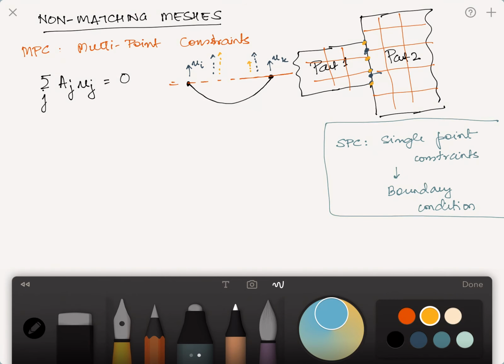So the equation in that case would actually look like this, for both cases. In the first case, the blue case, case 1, let me write it with a blue pen, then it's probably easier. So in case blue, where UI and UK have to move together and by the same amount, then I have A of UI minus A of UK is equal to 0, because they have to move exactly the same amount, so they are exactly equal. Even the direction has to be equal. So you can also write it as UI minus UK is equal to 0.